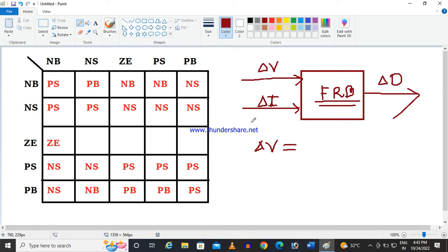Otherwise, say for this example my switching period is 1 millisecond. That means after each 1 millisecond the duty cycle will be updated for the PWM. Now the conversion for voltage and current, say it may take 400 milliseconds, as an arbitrary example.